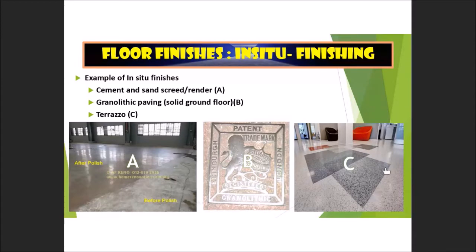Normally for the terrazzo, because you are required to have different shapes, they have to put the dividing strip or divider to make sure that when they pour the particles made from the smallest stone, you can get the shape of the material. So you need to have the divider in the measurement for the terrazzo.